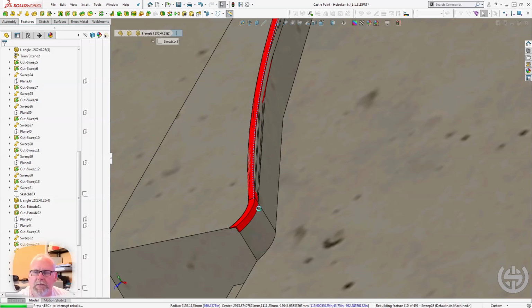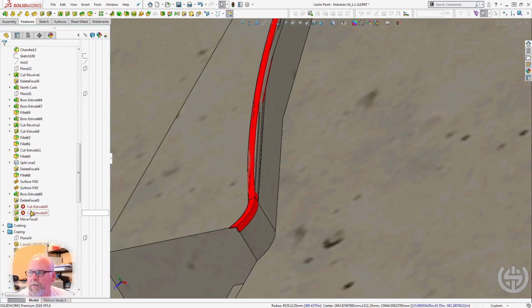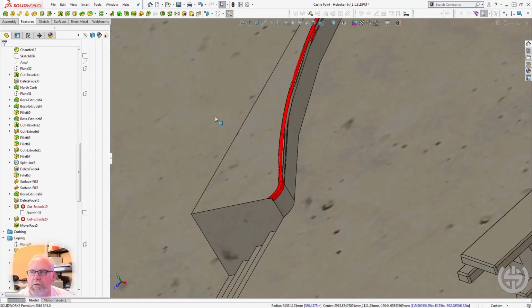And getting this angle iron to wrap around these sharp corners would be difficult. So this is a SolidWorks glitch, 2018. This is a bug. These two features right here, they're broken. The moment I rebuild it again, they'll be fine. And then if I go to the, it says it doesn't cut, but it does. So these are broken.